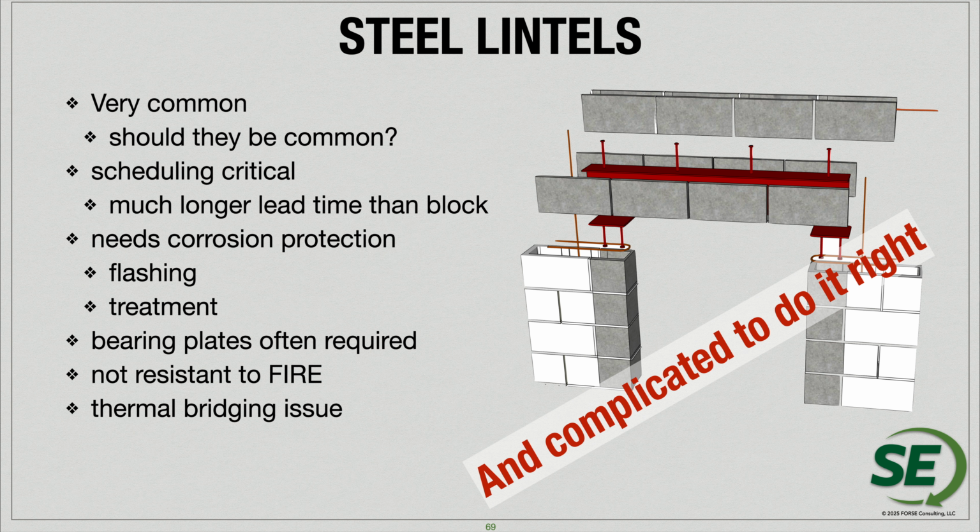Certainly, anytime that you have steel elements, we have to consider how the thermal transfer is going to happen for the design. But the other part of the thermal loading that you would have when you have a steel lintel is the steel is going to change size more rapidly than masonry walls. So what you have is a change in temperature is really going to create a stress for those steel beam bearing locations because the thermal load is going to change the steel size more quickly than the masonry around it, so the steel is either going to shrink or expand faster than the masonry wall, and it's pretty unforgiving if it's hard connected to the masonry elements.